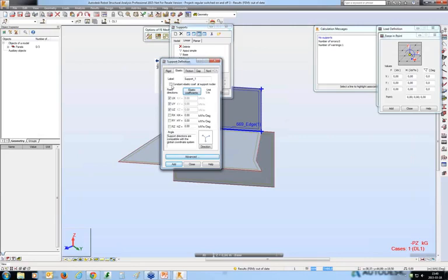If you mark this checkbox, then you will assign an identical support to every node generated along this line, regardless of the distance between the nodes. So make sure that it is switched off. I can hardly think of any situation where you need to mark this checkbox. It is much better because if you assigned this support manually to nodes, you would have to make sure that the distance among these nodes is the same, so that you have the exact value of elasticity for each support.